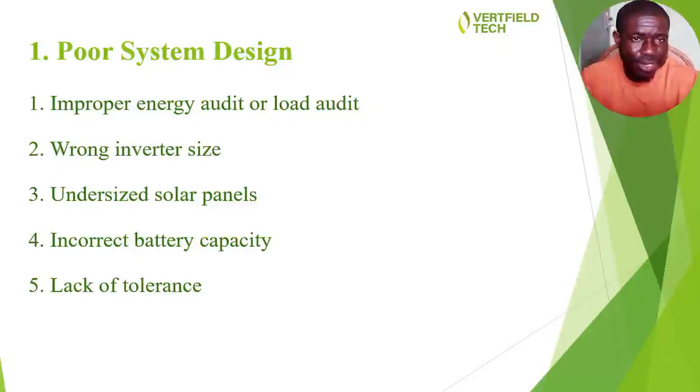Take for instance, if a facility is consuming 5,000 watts and you are to use a 5 kilowatt hour lithium battery to power that facility, how long do you think that 5 kilowatt hour lithium battery can run? That is what we're talking about.